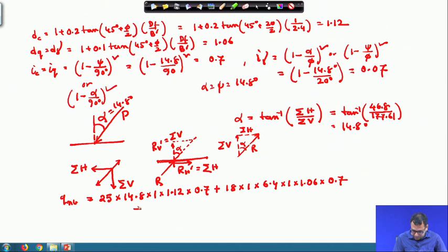Okay. Then plus half, unit weight is 18, then B dash is 2.4, then N gamma is 2.9, S gamma is 1, D gamma is 1.06 and I gamma is 0.07, minus DF is 1 and unit weight is 18.